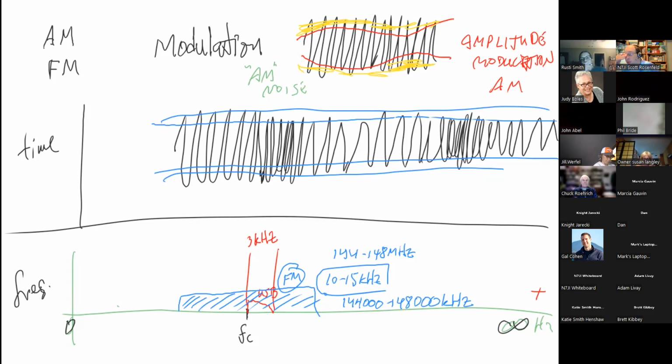It's known as the capture effect. It's also the reason that aircraft still use AM, because on FM, the stronger signal will win by a lot and the weaker signal will disappear, whereas on AM, you'll actually still be able to hear both. So an air traffic controller, if there are two stations there, actually wants to be able to hear both stations. And that's why air traffic control still uses AM. Where can single sideband phone be used in bands above 50 megahertz? That can be in at least some portion of all of the bands.